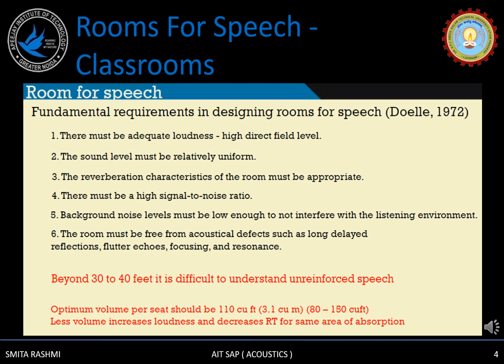And beyond 30 to 40 feet, it is difficult to understand unreinforced speech. Unreinforced speech doesn't mean we are talking about reflected sound. Reinforcement means we are using some kind of electrical instruments to reinforce our speech. So any kind of microphones we are using, that is basically reinforcing the speech.